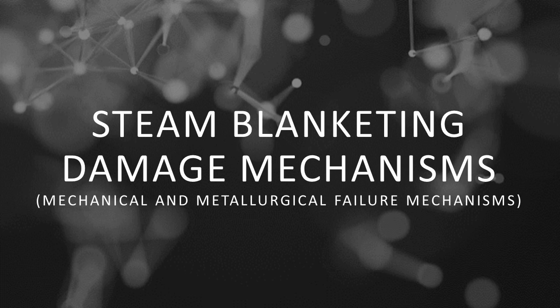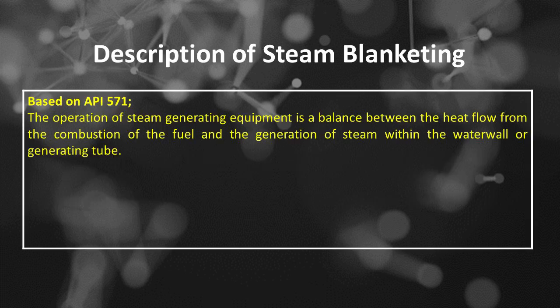Steam blanketing damage mechanisms is a part of mechanical and metallurgical failure mechanisms. Description of steam blanketing, based on API 571. The operation of steam generating equipment is a balance between the heat flow from the combustion of the fuel and the generation of steam within the water wall or generating tube.